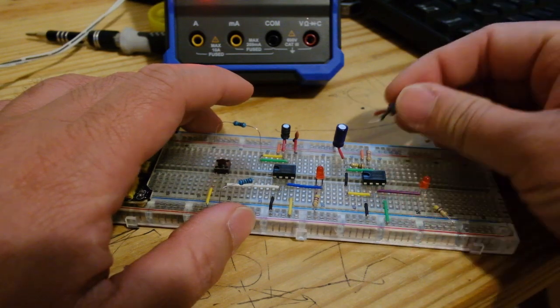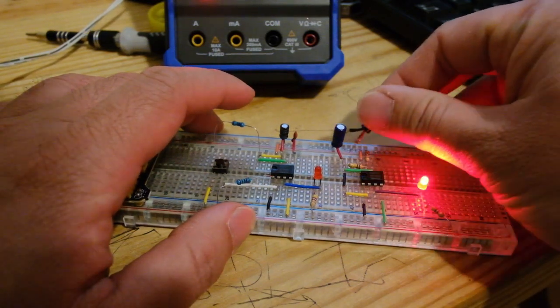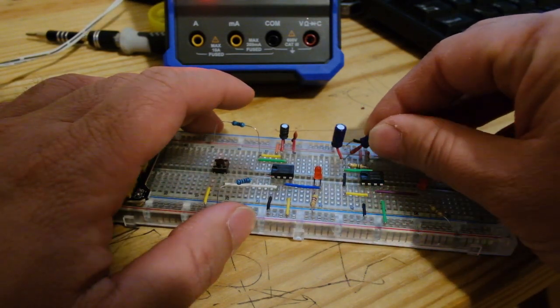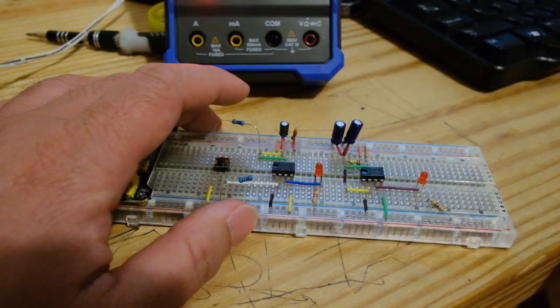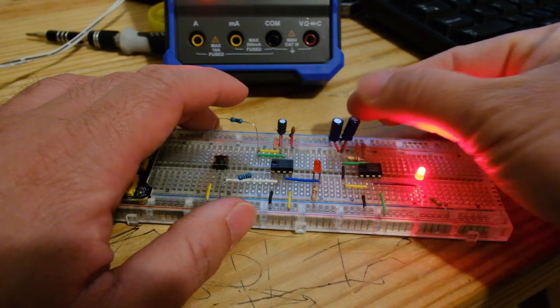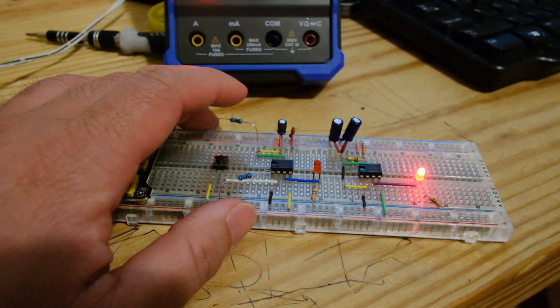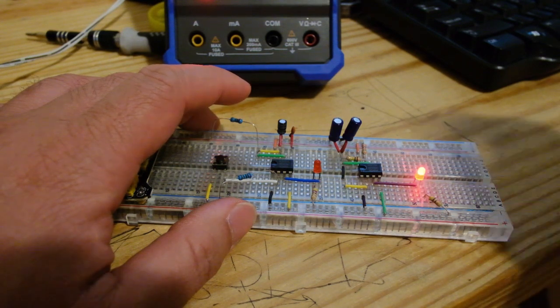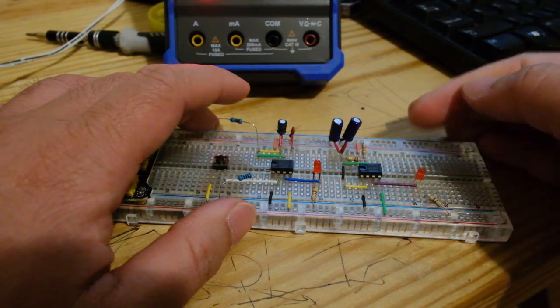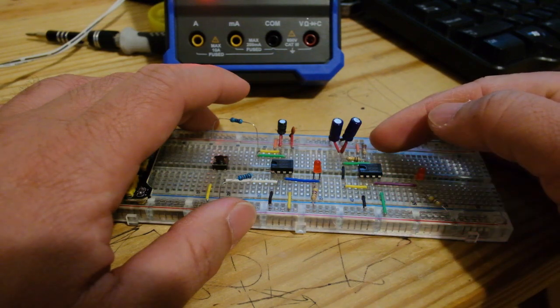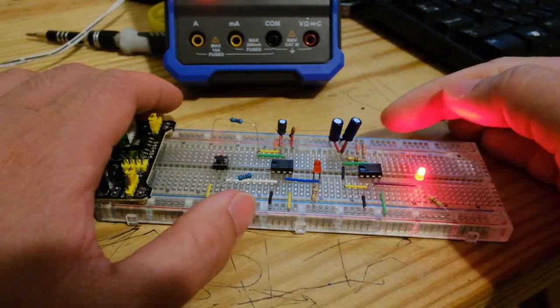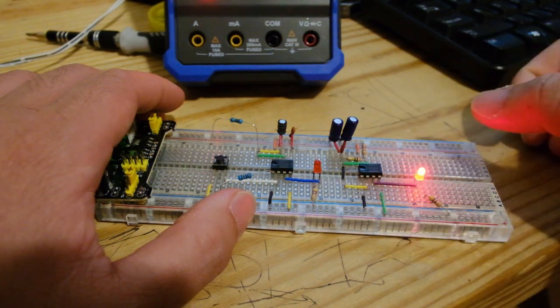Now, to further explore the capabilities of our circuits, we have introduced an additional 2.2 microfarad capacitor. By adjusting the values of capacitors, we can manipulate the charging and discharge times in the circuits. As a result, we observe a noticeable change in the frequency of the LED. The LED now exhibits a much slower pulsating rhythm, showcasing the influence of capacitor values on the overall timing characteristics of the circuit.